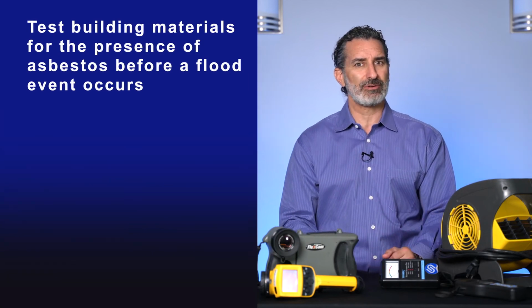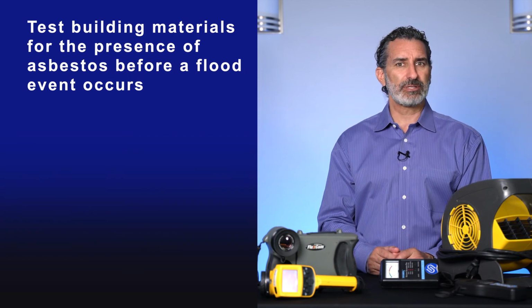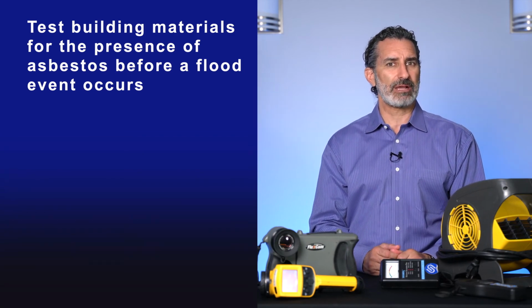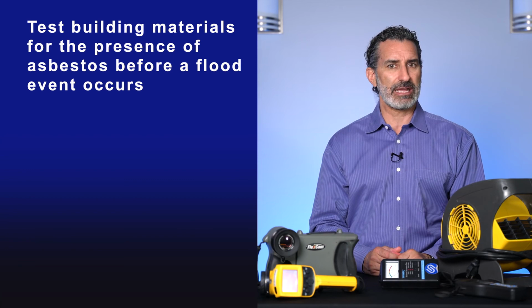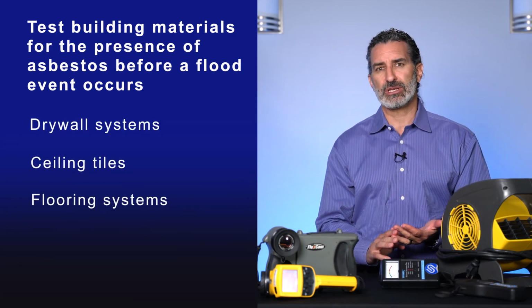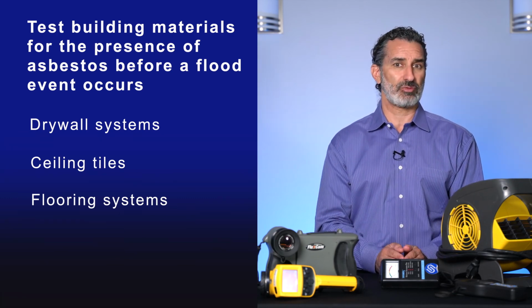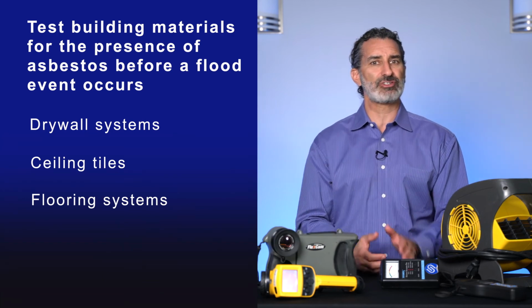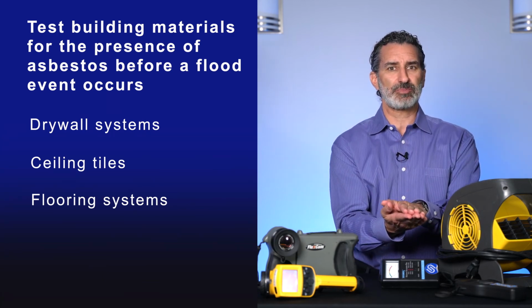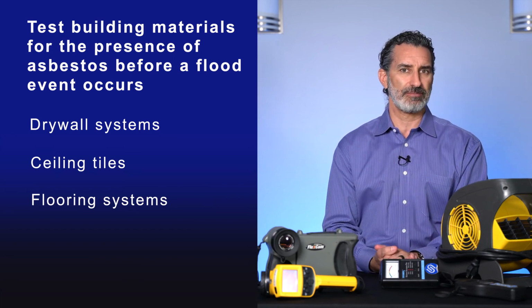The best way to avoid an asbestos disturbance is to test your building materials before you have a flood event. You don't necessarily have to test every building material in your facility, but the building materials that you're commonly contacting or that would be commonly affected by a flood, like drywall systems and ceiling tiles, perhaps even flooring systems. If you test those in advance, you know whether they contain asbestos or not. You have those records. So when the restoration company arrives, you just hand them the records. Here's what contains asbestos, here's what does not, and they will know what they can and cannot disturb.